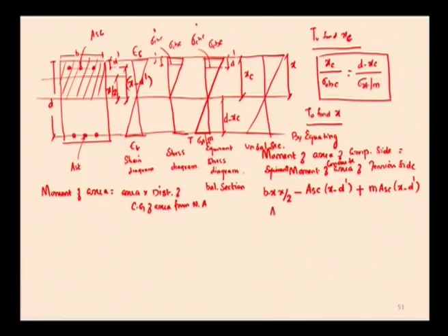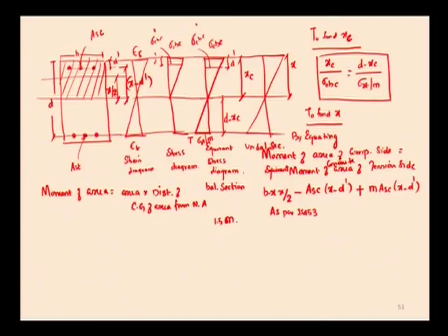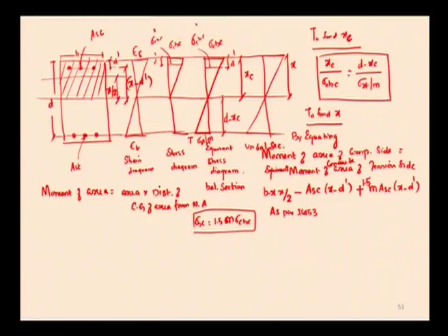As per IS 456, in compression bars where the compressive resistance of the concrete is taken into account, the stress shall be the calculated stress multiplied by 1.5 times the modular ratio. So, sigma SC is equal to 1.5 times the calculated stress at the compression zone. So, if it is multiplied by 1.5 times with the modular ratio along with the stress, this area should also be again multiplied by 1.5 times.